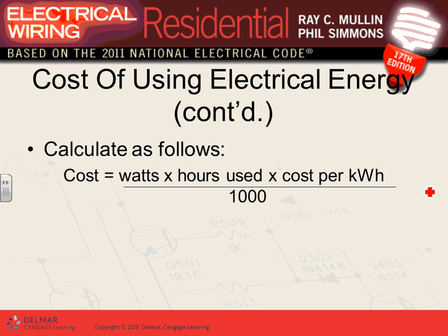Okay, here's the cost of the power, guys, in the US. Very simple. Say you have a 100 watt bulb. How long do you want to run it? Give me a number of hours. 5 hours? 5 hours. The cost per kilowatt-hour is 9 cents. Let's make it in dollars: 0.09. And why do you think we divided this by 1,000? Anybody, why did I divide this by 1,000?